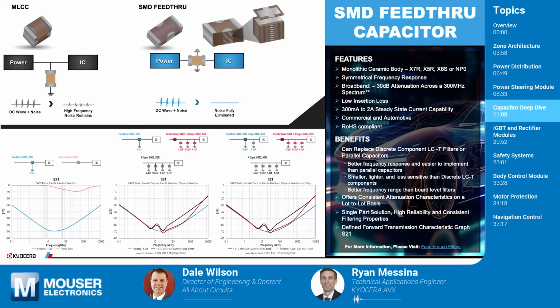And this is what I was referring to in, I think, the second slide that we talked about, the circuit diagram that had decoupling caps. Pretty much in every power line, VDD, the power in, power out, you're going to have a decoupling cap. And for the most part, what's really used in a lot of occasions is what you can see on the bottom part of the slide, where it has the 4 capacitors in parallel with one another coming off of a power line going into an IC. That's in order to get good power quality, stable power. So you're filtering out all of that noise.